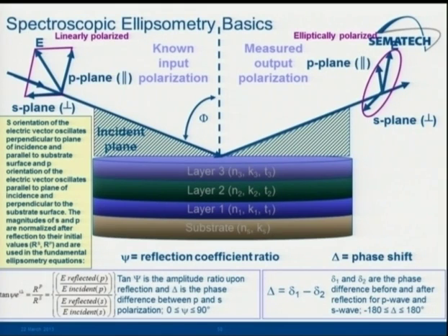So ellipsometry in its basic sense has been around for quite a few years. The idea is you take an optical light beam, typically either a single wavelength or a small number of wavelengths of light. You run it through a polarizer, so you know the polarization coming in. You bounce it off an optical surface that, by interaction with the elements in the different layers, causes a rotation of that polarization, and then you measure how that polarization changes coming out.